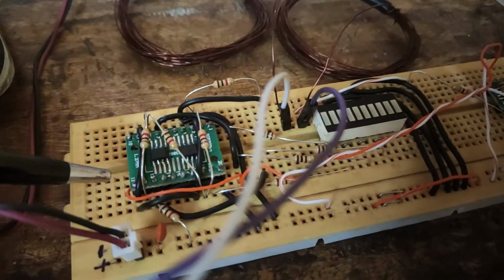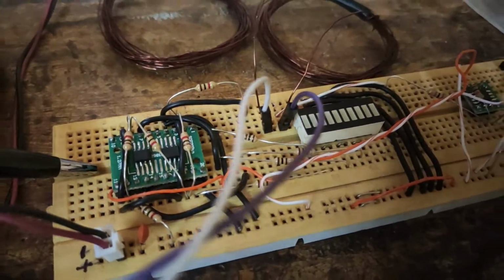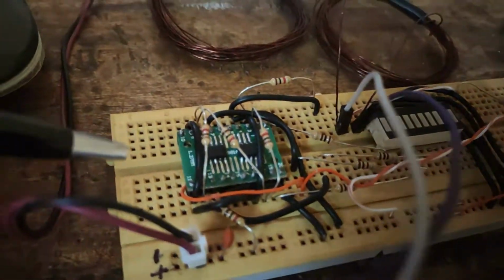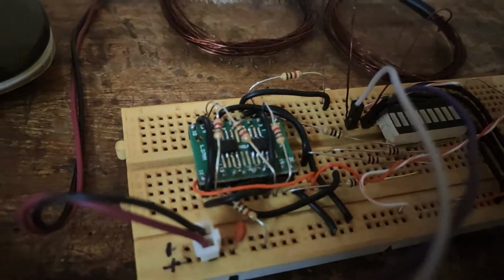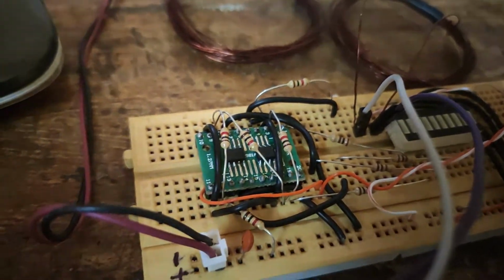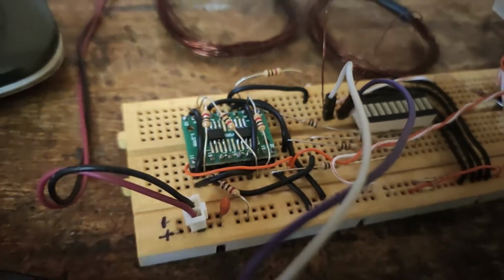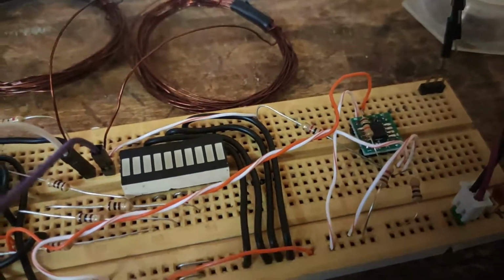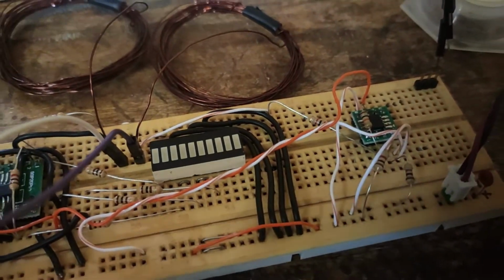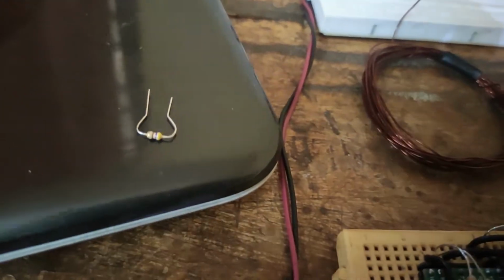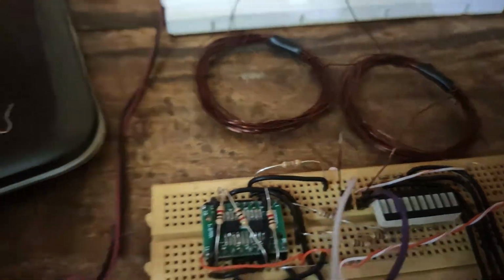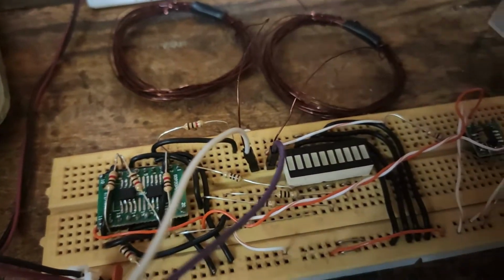These are LM393 TI dual comparators. Since I readily did not have the driver for this bar LED, I just designed one using 4 comparators. It would just compare whether the voltage is high or low with regard to the reference, and then would drive this bar of LEDs. This is the drop resistor which will go here to the loop so as to interpret the voltage, but I have picked it up and kept it outside now just to measure the current.